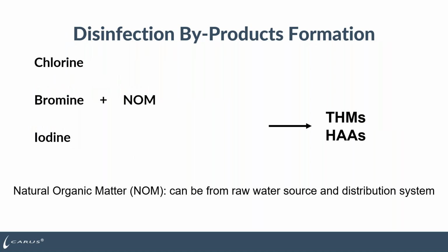So in the case of disinfection byproduct control, what we're looking at is that there's natural organic matter in the water. So typically we talk about what's the starting TOC, or total organic carbon level, in your water. That TOC is reactive with a variety of things, but the most common is when you add chlorine for disinfectant, it will react with that natural organic matter, the TOC, and it will form THMs and HAAs. Once they form, you're either going to have to absorb them to remove them on carbon or strip them out of solution by aeration, but they're going to stay in solution unless you're doing a removal technique.